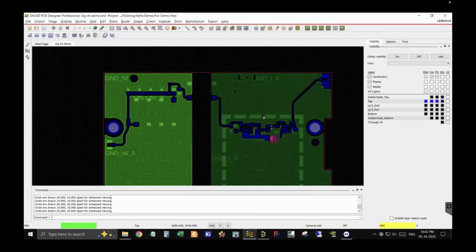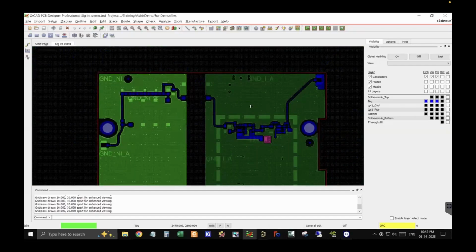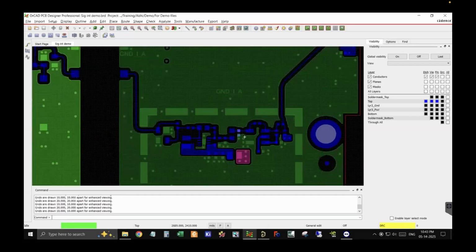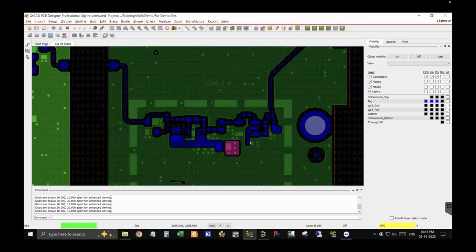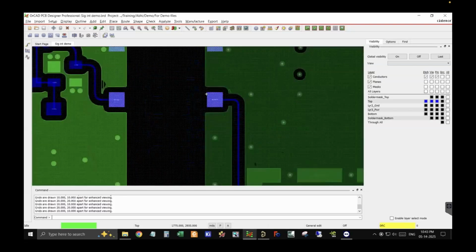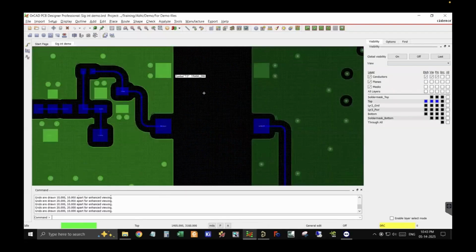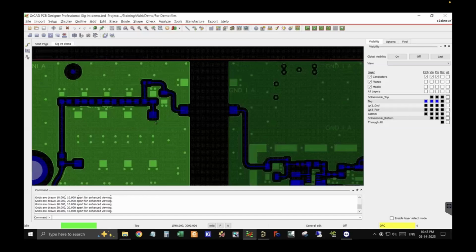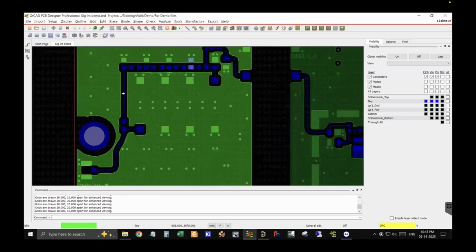Yeah, so I'll just show you what we at Sierra Circuits do while designing high-speed RF lines. So this is a board which works on a frequency of approximately 30 megahertz to 3 gigahertz. There is a circuitry over here which involves a lot of inductors, mostly LNAs, chokes, then filters, and there is this isolation transformer over here, which is basically separating the two grounds on the other side. And there is a band pass filter, which is then passing this signal to the SMA connectors.